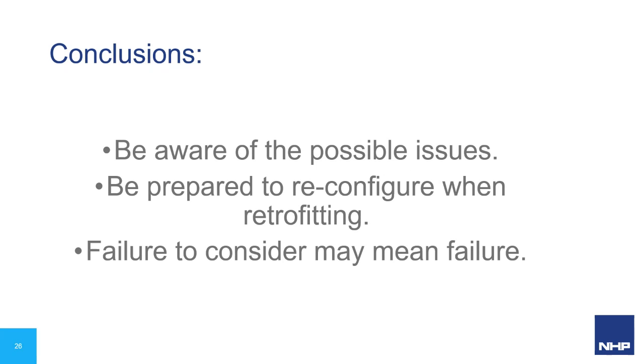So in conclusion, we need to be aware of all of the issues. Circuit breakers may trip. They do so for a good reason. So we've got to consult the motor specifications before choosing the protection and control equipment. We need to consult the manufacturer's tables for appropriate combinations of the circuit breaker, contactor and overloads for the application.